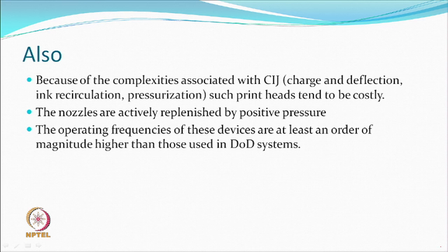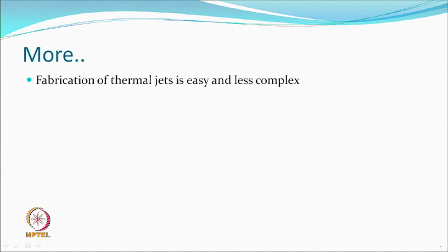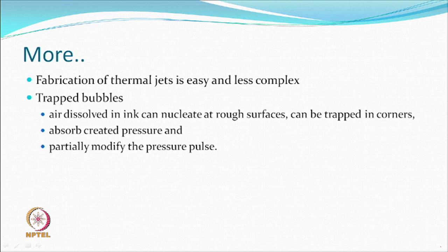The nozzles are actively replenished by positive pressures, and the operating frequency of the continuous inkjet print heads is generally about an order higher than those used in the drop on demand systems. We also appreciate that the fabrication of thermal jets, that is thermal inkjet, is relatively easy and less complex.